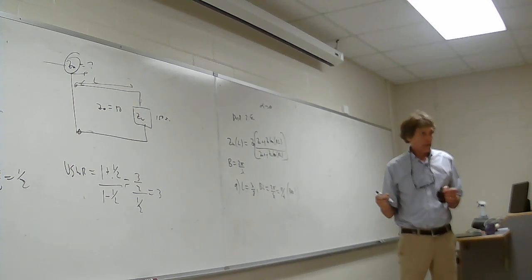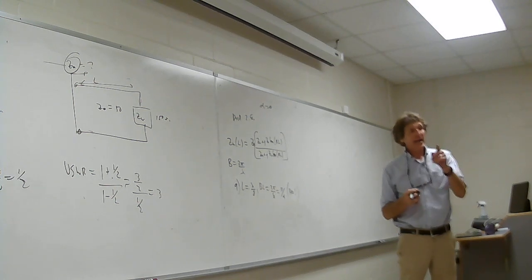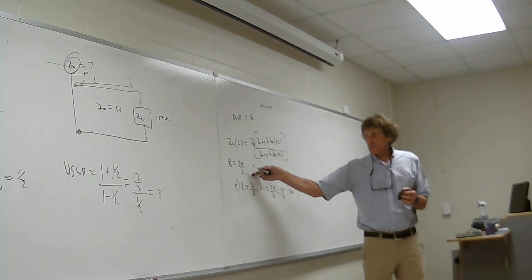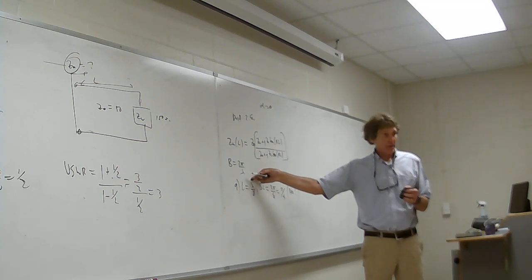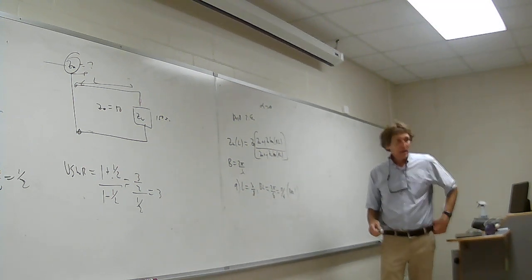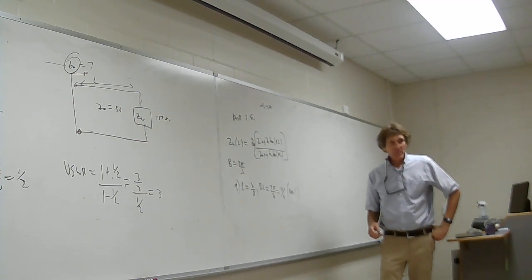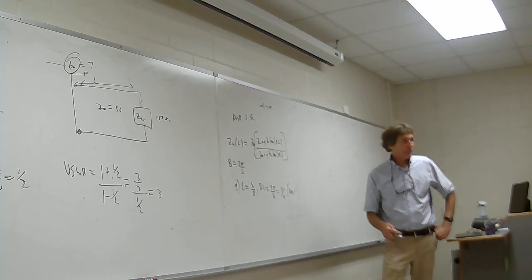Can you explain how you got that answer again? All right, he says L is lambda over 8, right? Beta is defined as 2 pi over lambda. Oh, I see, okay. Yeah, so if I have 2 pi over 8, the lambdas cancel automatically. I get pi over 4 radians. Now, what's the tangent of pi over 4, of 45 degrees?